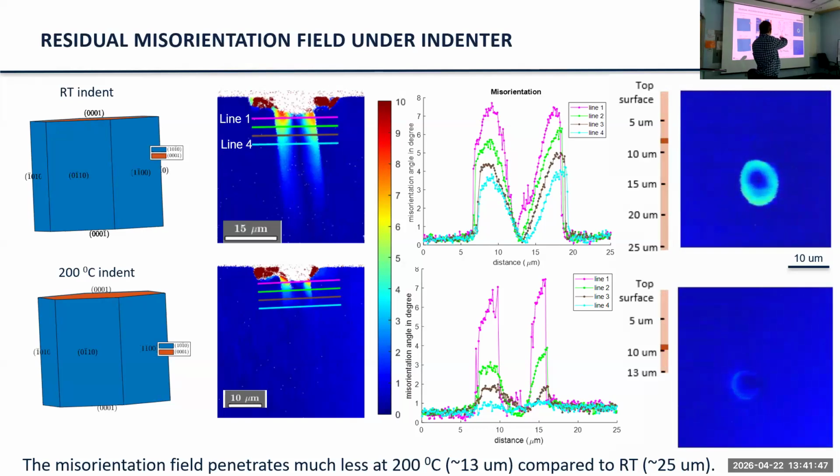The material is really being pushed in, and we'll see that we can interpret these misorientations as arrays of dislocations. So those are pushing like the snowplow out, but they have this very strong barrier because the stresses drop off very quickly when you get outside the contact point of the indenter.